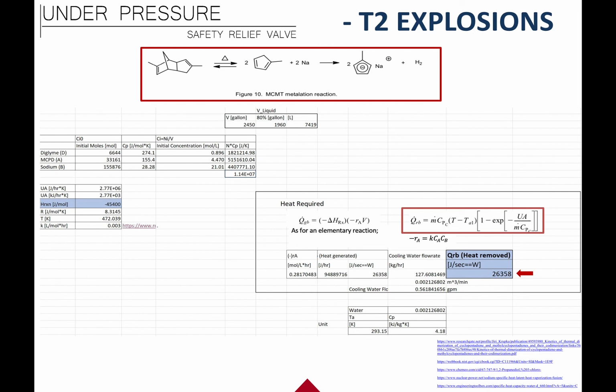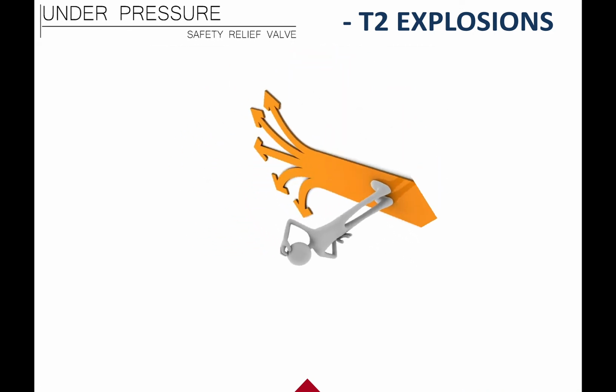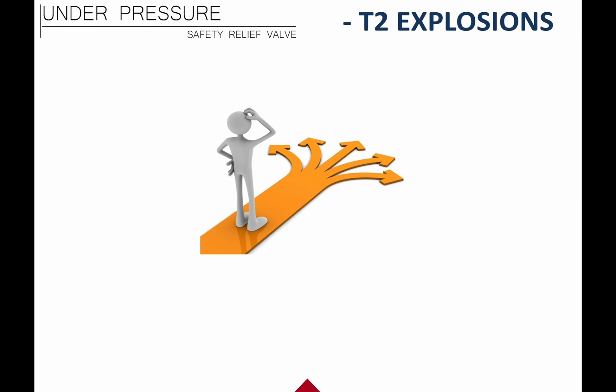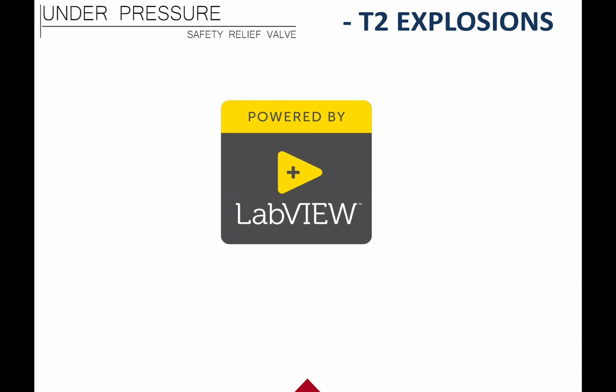So in order to cool the batch reactor, the cooling system would need to give off energy equal to or greater than that amount. Possible alternatives are to upscale the experiment, or further research for smaller scale safety relief valves is required to enable the design to become applicable. LabVIEW should be programmed to randomly switch the actuated valves on and off.